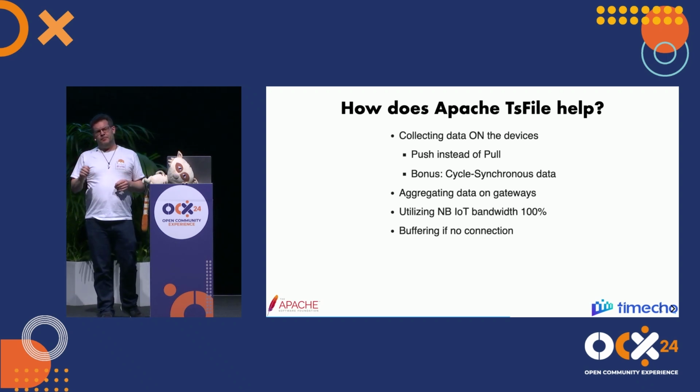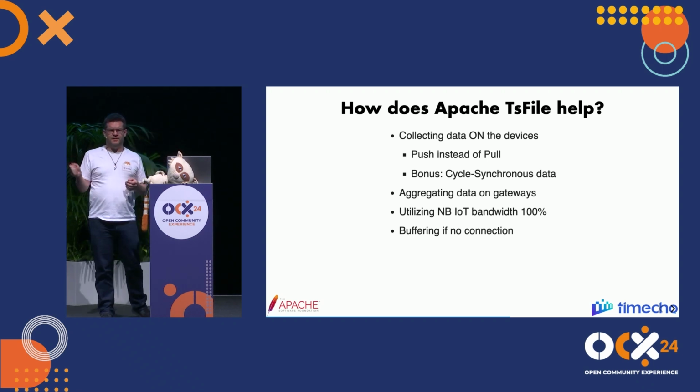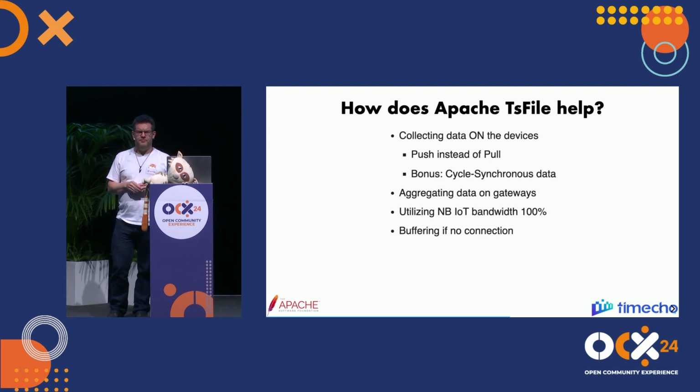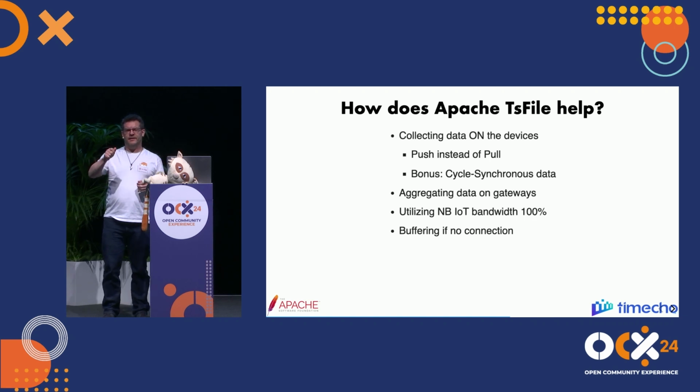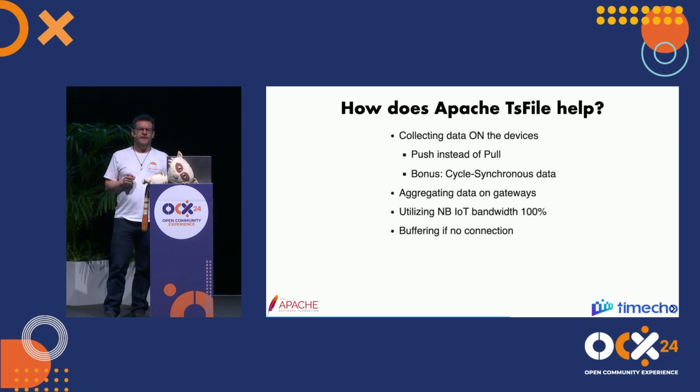So we would be implementing libraries for the various programming OT environments, like for TIA Portal, a library you pull in. For CodeSys, we would be providing libraries where in your PLC program you say, "Now write this value and this value and this value," and it would be stored with a timestamp. And as soon as, let's say, the item leaves the machine, then we send off this TsFile data in one MQTT packet, and we're done.